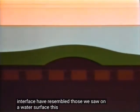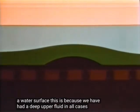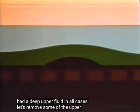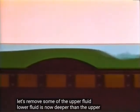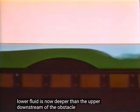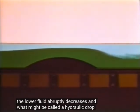So far, phenomena at the interface have resembled those we saw on a water surface. This is because we have had a deep upper fluid in all cases. Let's remove some of the upper fluid. The lower fluid is now deeper than the upper. Downstream of the obstacle, the depth of the lower fluid abruptly decreases in what might be called a hydraulic drop.